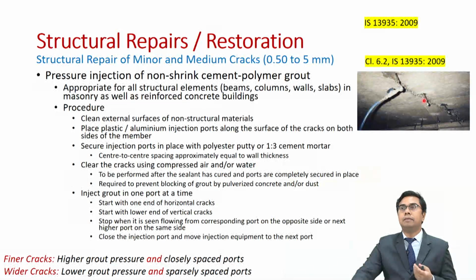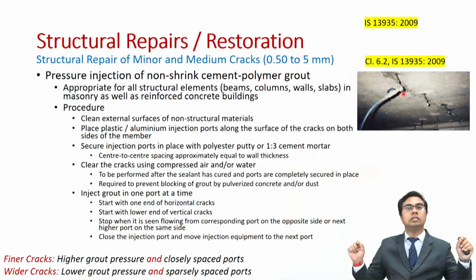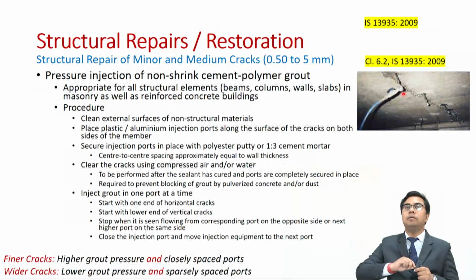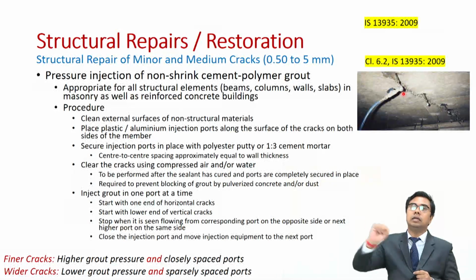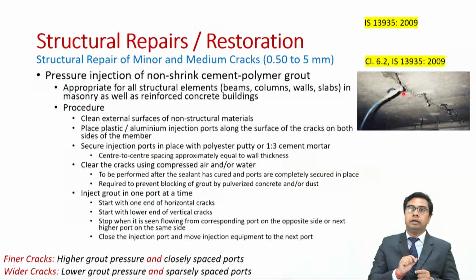This is based on practice, and then we connect the injection equipment to one of these ports. Now, which ports shall we be connecting first? In case of a horizontal crack, we can start at either end, but if you have a vertical crack or an inclined crack, then we will start with the lower end,